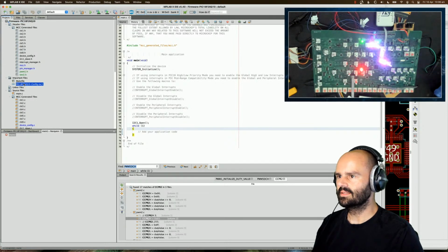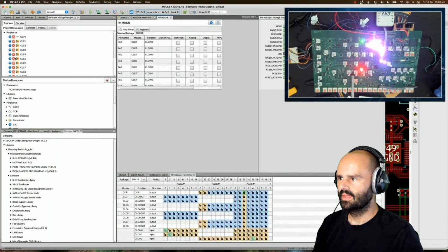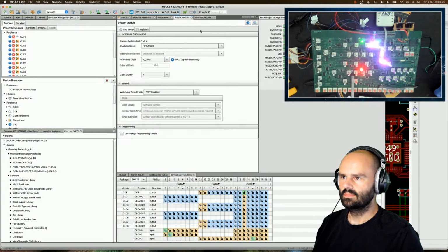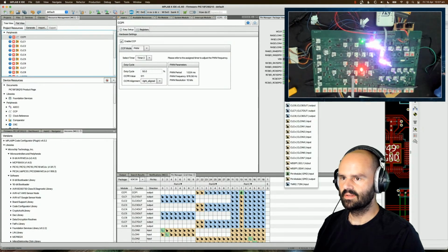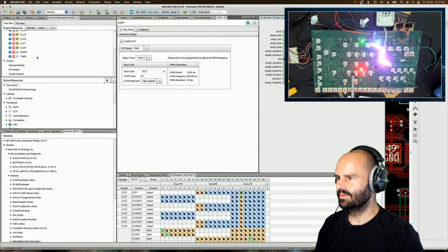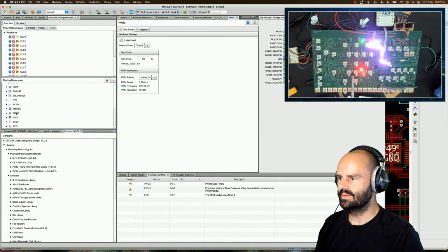and I think what we need to do is go into our configuration. Here we go. And I opened a lot of stuff. I'm going to enable two things. So we've got CCP1, but I'm also going to enable one of the PWMs just to have a comparison of configuration modes, see which one's making sense. So I'm going to add PWM3, which is pulse width modulation, basically a way to generate a variable voltage.